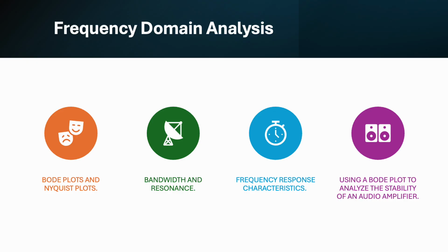Frequency domain analysis is a powerful technique used in engineering and signal processing to study the behavior of systems and signals in terms of their frequency components. Unlike time domain analysis, which examines how a signal changes over time, frequency domain analysis focuses on the signal's constituent frequencies and their magnitudes and phases. This approach is particularly useful for understanding how systems respond to different frequency inputs, identifying resonant frequencies, and designing filters.